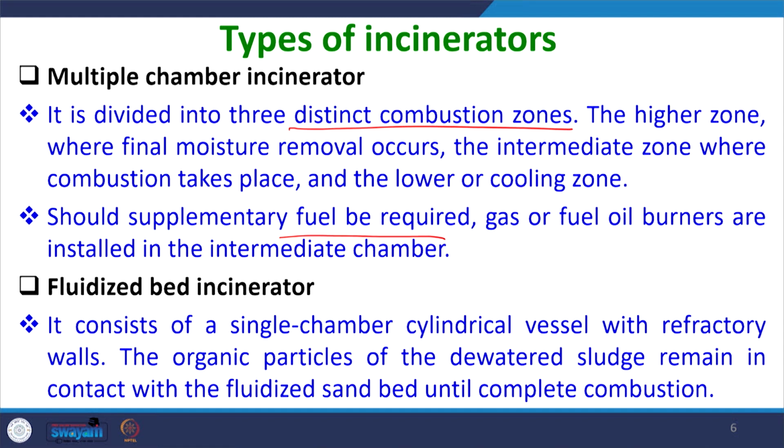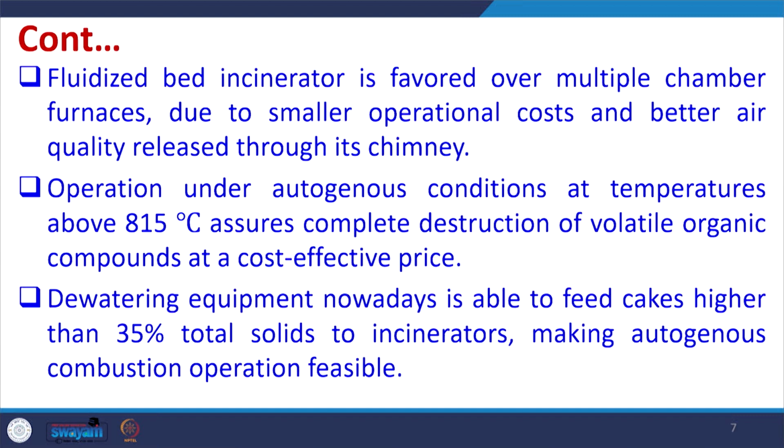Then there is another category of incinerator called the fluidized bed incinerator. It consists of a single chamber cylindrical vessel with refractory walls. The organic particles of the dewatered sludge remain in contact with the fluidized sand bed until complete combustion occurs. The fluidized bed incinerator is favored over multiple chamber furnaces due to small operational cost and better air quality release through its chimney.